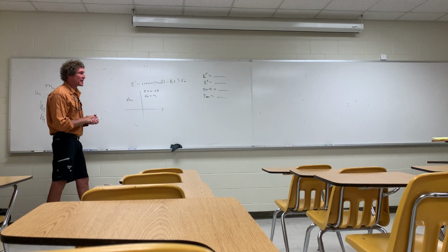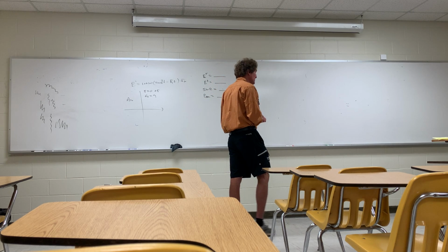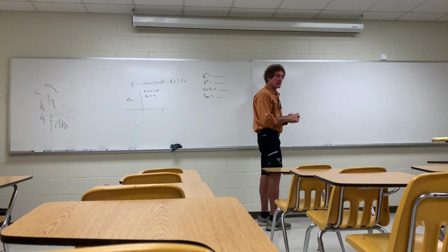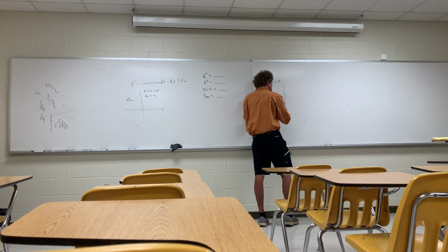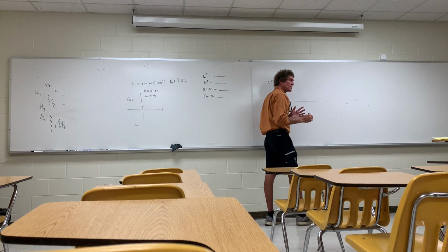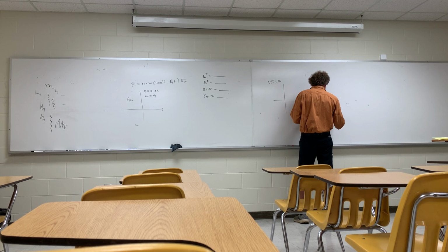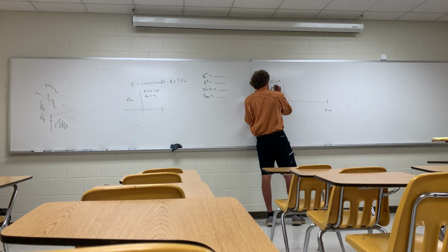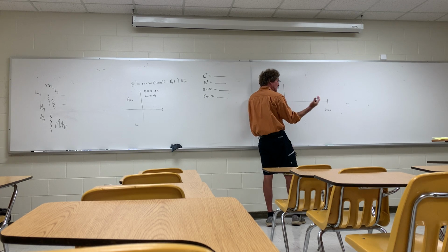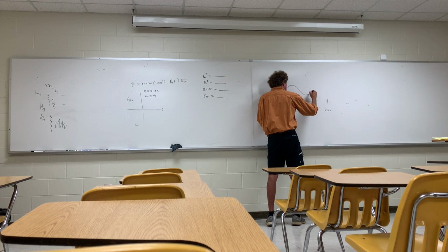Do you remember what the standing wave ratio was back in the day when you had a transmission line? SWR was usually VSWR, right? Voltage standing wave ratio. If you have a transmission line, with z equals 0 here, and you looked at the magnitude of the phasor voltage, which is the sum of the reflected and the incident voltages, you would get something like this.